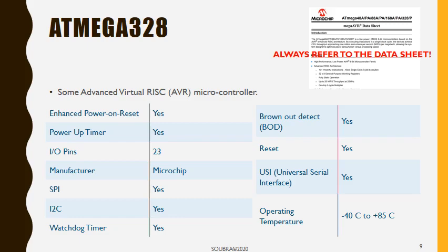Question number 2 for everyone that is here. Let's imagine a military application. All right? What would be the temperature operation ranges of microcontrollers that are used in military systems, and why? Way wider. So instead of stopping at plus 85, let's say, it can go up to 150 or something like that. And this will cost a lot more money, for sure. But why is it important?